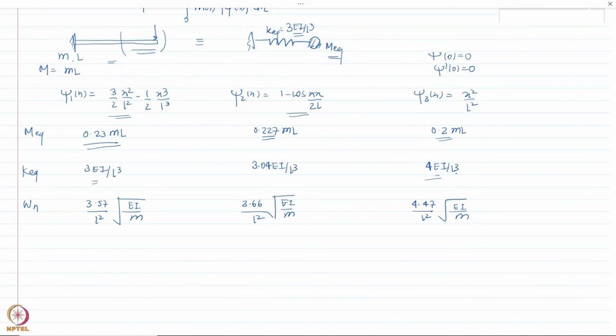So typically, a static deflected shape of any structure can be assumed to represent the dynamic deflected shape, although it won't be exactly equal. However, I know that a static deflected shape would always, because it is constrained by the same boundary condition, satisfy the displacement boundary condition.